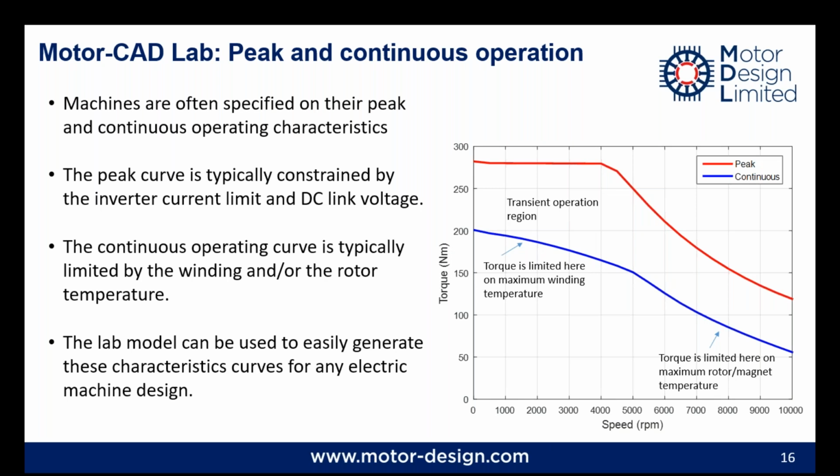And we solve all this together to give us a maximum continuous operating curve. And we're going to show one of these at the end of today. And obviously to calculate this, including AC losses, is very important, particularly to understand what the continuous performance capability is of a design at the higher end of the speed range.